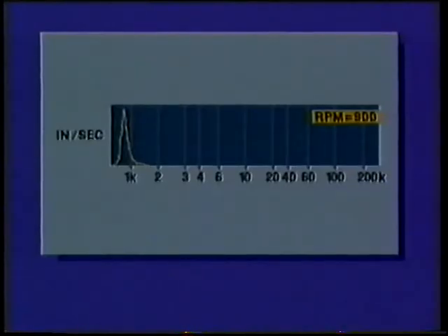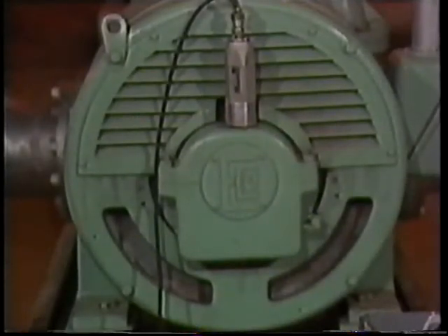What about angular misalignment? What are its primary characteristics? In the case of angular misalignment, 2 shafts are at an angle to each other. Vibration produced by angular misalignment would usually occur at a frequency equal to the shaft's RPM. In the case of angular misalignment, only one force is operating on the shafts. This force will be picked up by the analyzer's probe at the shaft's bearing.